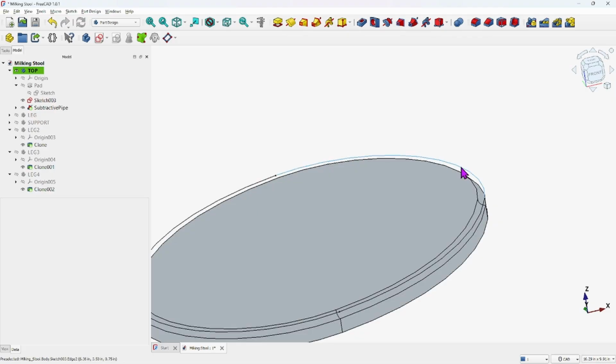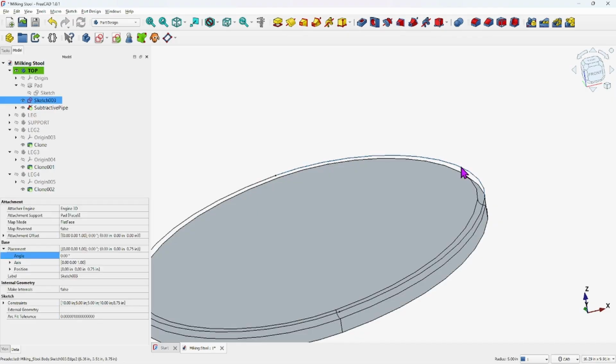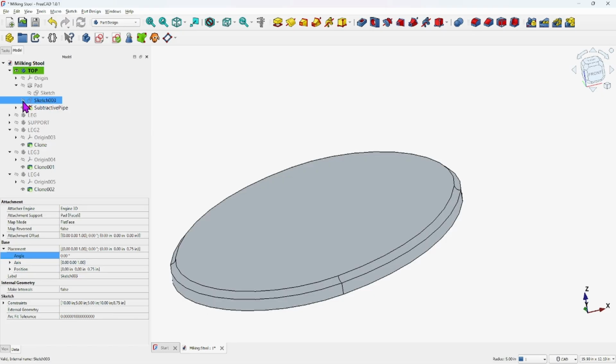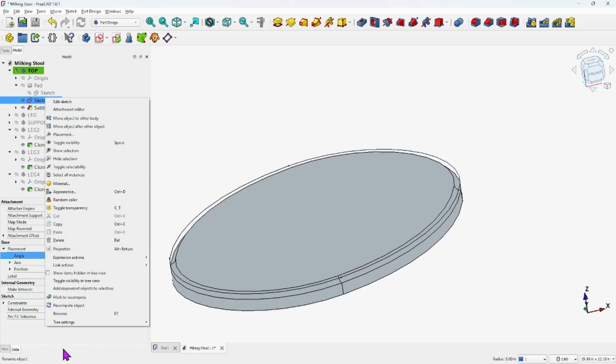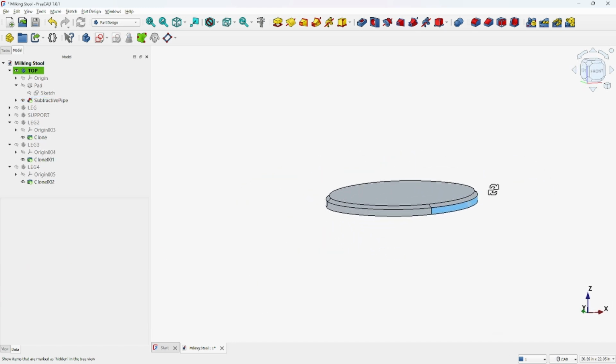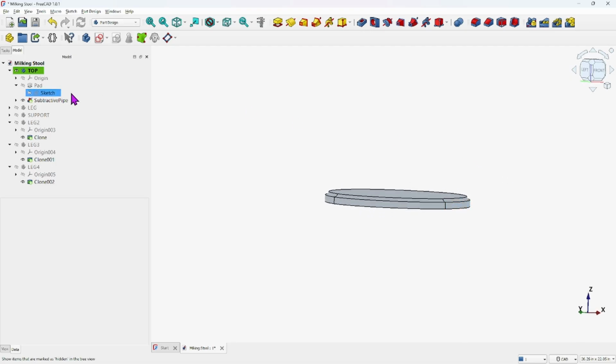Now that line right there, oh, that's the sketch. Sketch is turned on. So now I'll turn the sketch off. You see that right there? Sketch 3, just turn it off. Actually, we didn't even need that sketch. Turn it back on to show you that I can delete that sketch since we used the edges instead of a sketch to roll it around. Look at that. Okay, now we have routed it successfully. Close it.